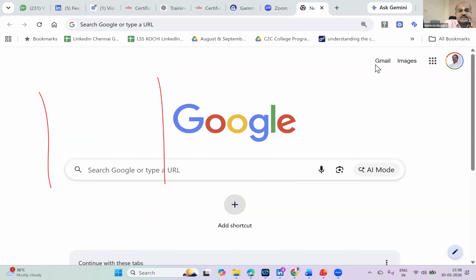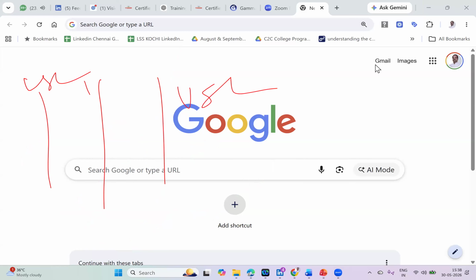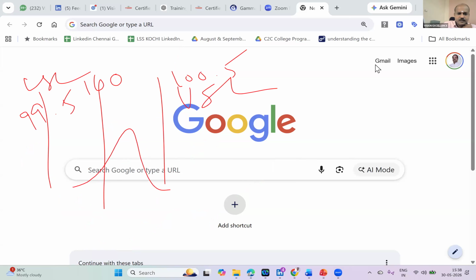Now, there is USL, there is LSL. And customer target is 100. USL is 100.5 and LSL is 99.5. Now, customer tolerance is understood? 100 plus or minus 0.5? Now, my process is operating like this. My process center, I'm telling you, X bar, is 100.2. Now, please tell me, is this process shifted right side or shifted left side?